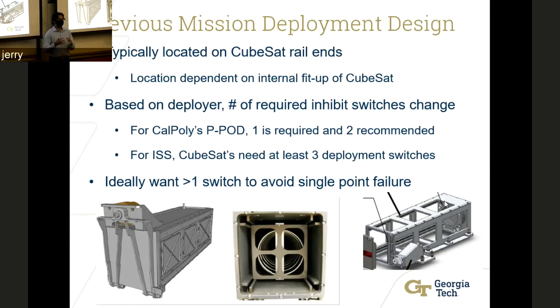The way these CubeSats get launched is that they all get put in there, they get launched up to the ISS, and then from the ISS, this JSSOD is sent out. And then there's a spring, as you can see here, that pushes the CubeSats out, and then they deploy from there and perform their normal activations.